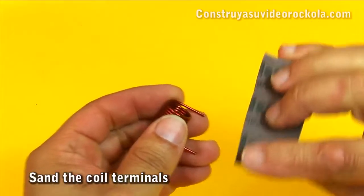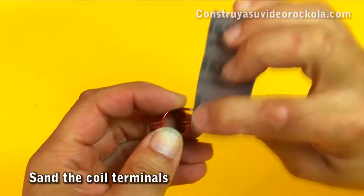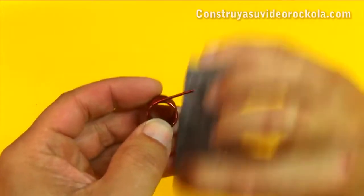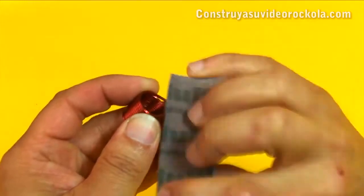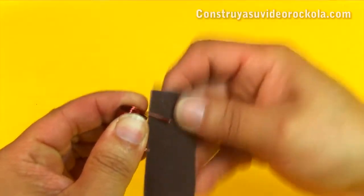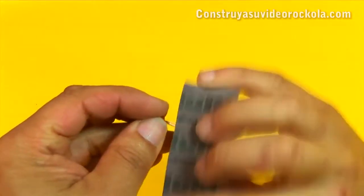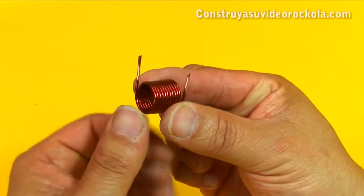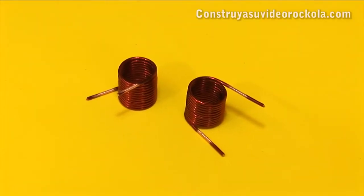Now, as the coil will be welded to the PCB, we must remove the dielectric varnish from its terminals, so that later the solder will stick. For this we use coarse grit sandpaper, in this case, grain 80. We must be careful not to mistreat the coil, not to deform it, and also not to scrape the spiral's enamel. This work is done with great care. We make 2 equal coils.